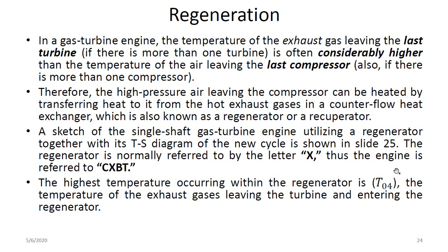So if you've got CXBT, it means that you've got a regenerator between the compressor and the combustion chamber. So CXBT means you've got one compressor and one turbine, but in between the compressor and the turbine there's this regenerator.